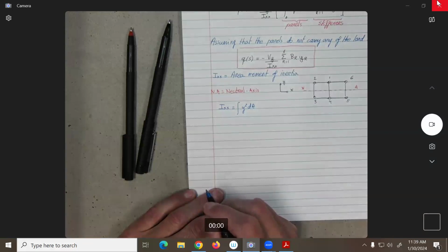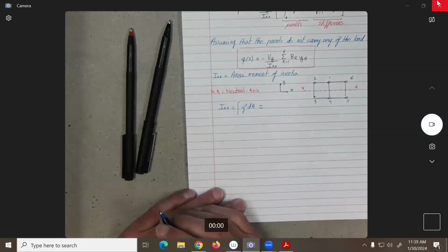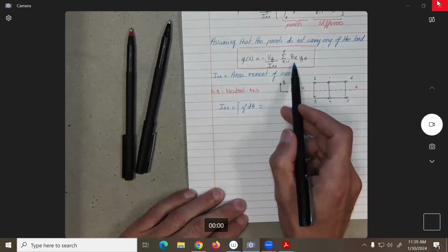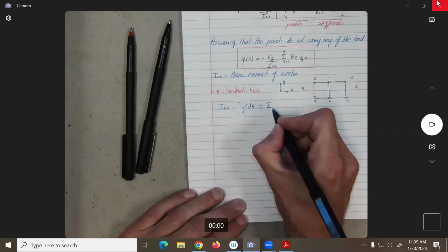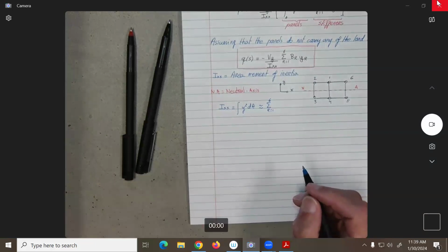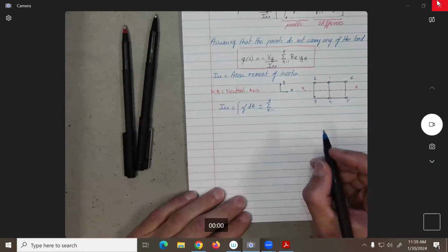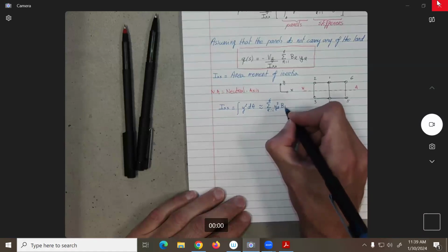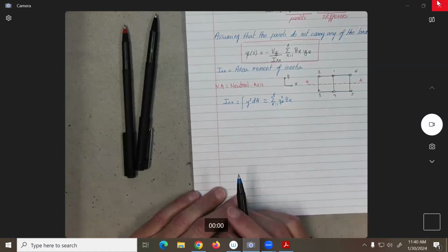Is y squared dA, okay? So really, in our case, when you look at this, dA should be equivalent to what? To our base, no? To our boom area. So we could say that this would be basically equivalent, and you know that the integral sign is basically the same thing as doing the summation. Not going to get into details, but integrate is like doing the summation. So we could say that we could do the summation of the y sub r squares times the b sub r's about the neutral axis.